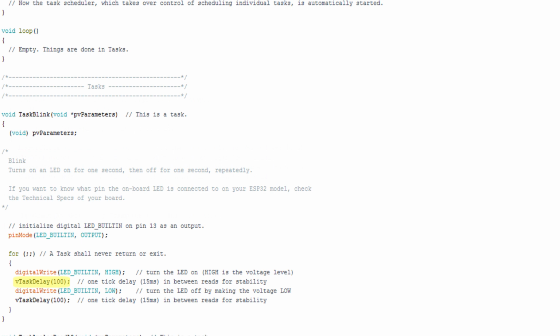The end result is the same time delay of thread execution, but with FreeRTOS, other work can be performed during this downtime. This is a key feature of FreeRTOS, the ability to quickly and easily block task execution while allowing other tasks to continue. This delay controls how long the LED is turned on before the next line executes.